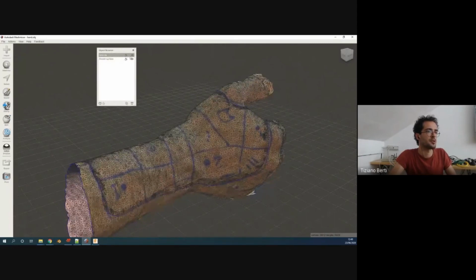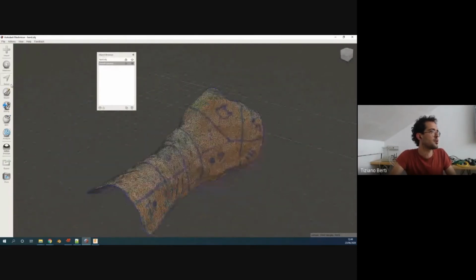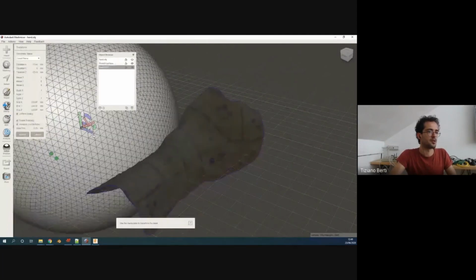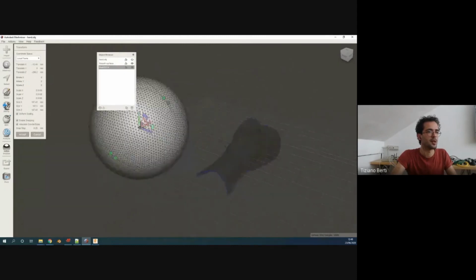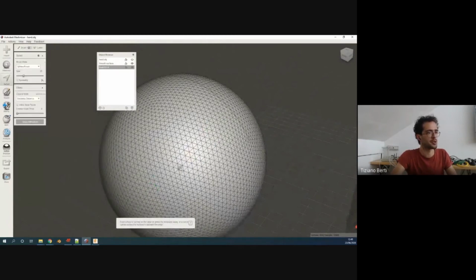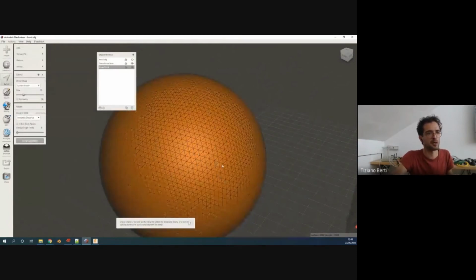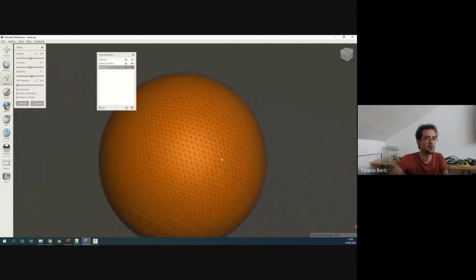We have the smooth surface. I will go a bit faster right now. So my standard operation is always to understand what I'm doing with this surface at the end. So I want to use one method which is the fastest way to get a breathable surface, and I just drop a sphere right here just to see the process. So I will first select my object, make an offset of it, so to gain some distance from the original surface.